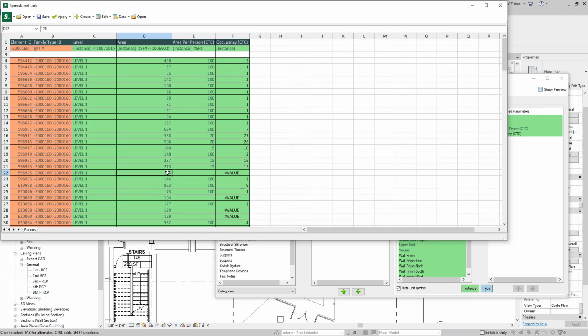Now, I do have to handle scenarios where a room perhaps is not occupiable or perhaps doesn't have a square footage. So I may have to write some extra logic in here, like if error. So I'll do that right now. If error, do the thing, and if there's a problem, just put nothing in there instead. And so what it will do is, if it runs into a scenario where it can't do the maths, it will just put nothing, right? Some simple things here, but I can run these numbers and figure out what I want my formula to be.